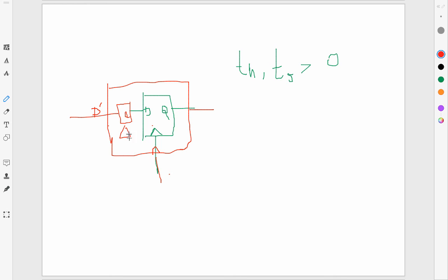I can play the same game in the reverse direction. Let's imagine a flip-flop where the clock had some delay added for some reason. Maybe a lot of wiring delay or something like that, or maybe the clock was buffered. In that case, the reverse thing can happen. Setup could become negative, and hold may increase. The main thing that matters is that setup plus hold will be constant, and the effect of all these other things is to shift that budget around.